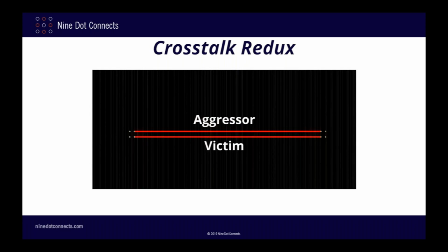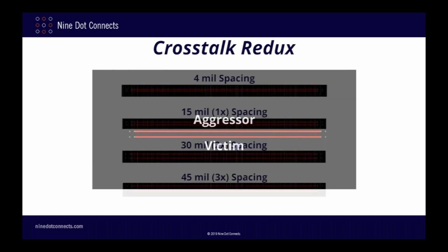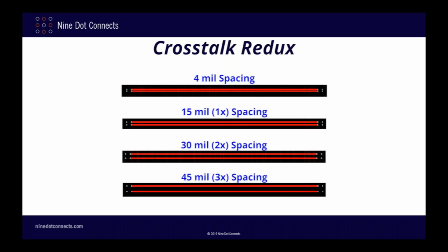Since I'm able to assign component models from within the simulation software, I don't need to have any footprints here. Instead, I'm just using vias to mark the various endpoints and ground connections. I've made 4 variations of this design, changing only the spacing between the traces. This will let me explore what effect the spacing has with no other variables in the equation.